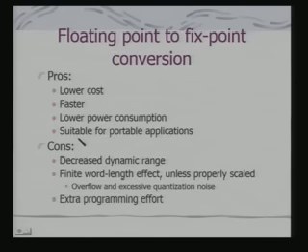When you do that, what are the advantages? Obviously, you have lower cost, less computational overhead in terms of hardware, faster speed, and lower power consumption, and that is what is suitable for portable applications. And obviously, the problem is the finite word length effect: unless properly scaled, you have overflow and excessive quantization noise. And it requires extra programming effort.